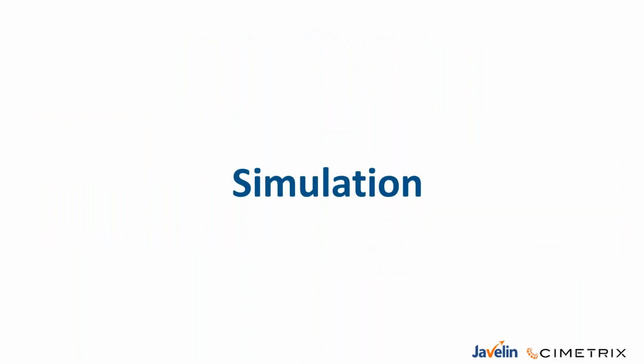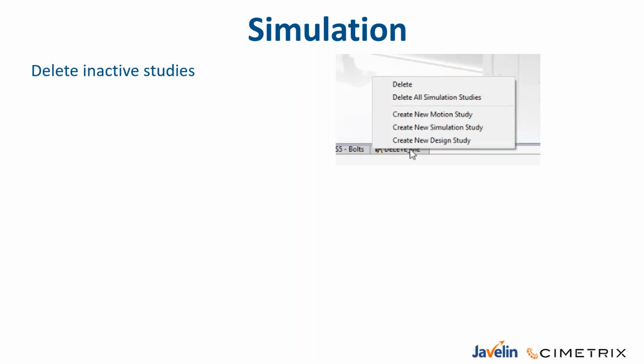Next up, let's talk about simulation, because simulation has seen some nice performance improvements. Integrated simulation, having your CAD data and your simulation data tied together so that you don't have to redo your study setup anytime you make a design change, has for a long time been one of the big benefits of SOLIDWORKS simulation. Now we're seeing some very cool things to increase general usability. In 2020, we can now delete any inactive studies without opening them. Before, you had to actually load the study, load the results, then you could hit delete. Now you can just right click and delete without loading it.